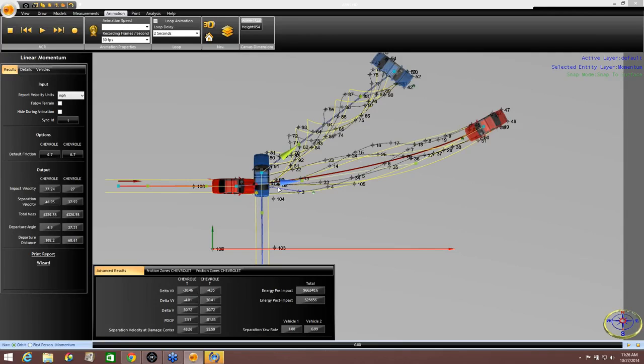As a matter of fact, when you look at the video of this, when the red car hits the blue car and the blue car spins its first spin around, the rear tires aren't even on the ground. They're off the ground for a part. So what kind of deceleration rate is there? You're down around 0. For a very short distance, but you're down around 0.